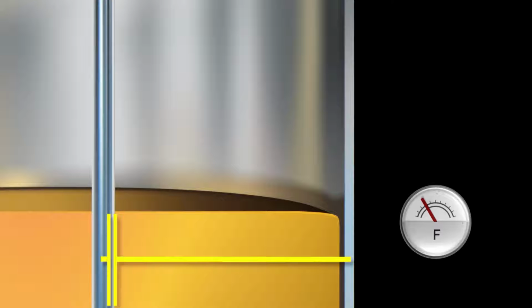The capacitance change in non-conductive liquids, which are normally oils and solvents, is caused by higher dielectric constants of the medium in relation to air. The non-conductive medium forms an additional capacitor to the tank wall connected in series. It determines the total capacitance. If the level rises in the tank, the area of the capacitor increases proportionally.